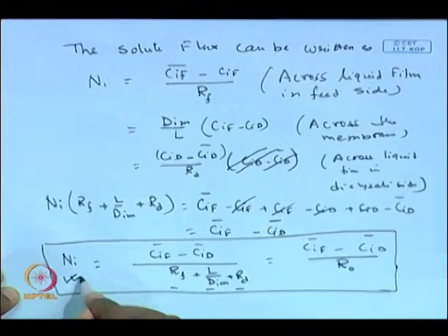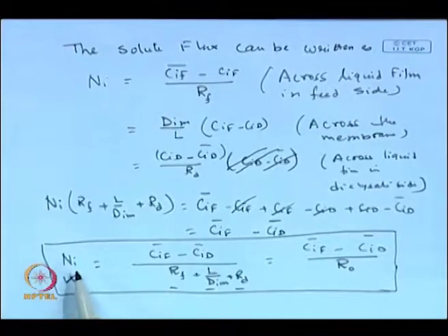In the process, the most important thing is to estimate, given the performance, the concentration to which you would like to reduce the value from the feed concentration, etc. It is very important to know the transmembrane solute flux. To estimate that, I discussed in the last class. If your target is to remove this many kg per hour, then you can find out the membrane area required to serve this purpose. So, it will be extremely helpful in the design of any dialyzer.